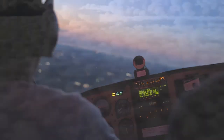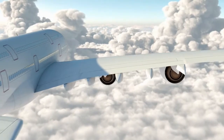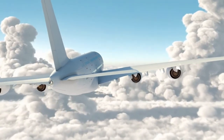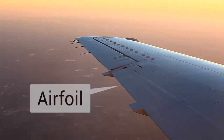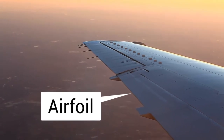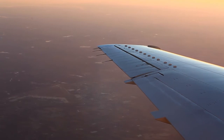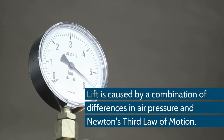While most of these forces have relatively simple explanations, the theories behind lift have varied greatly. All of these ideas center on how the air moves over the wings of a plane, also known as airfoils. While some people or books will reference something known as Bernoulli's principle, it turns out that this force is generated by a combination of pressure differences and Newton's third law of motion.